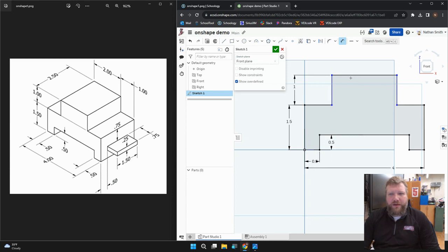All right, so now I look up here. I have my 2 inches across the top. And because I had set these equal to each other, if this is 2, these 2 lines are equal. They have to be 1 inch if the whole length is 4. If I again go in and try to add that dimension, it'll allow me to, but it's that lighter gray, and that's a bad idea. All right, so now everything is turned black.